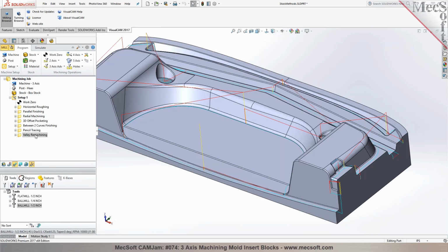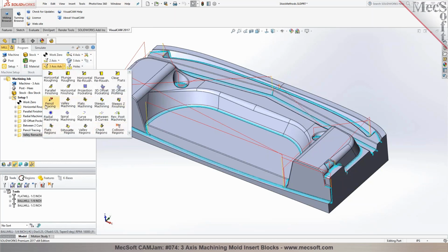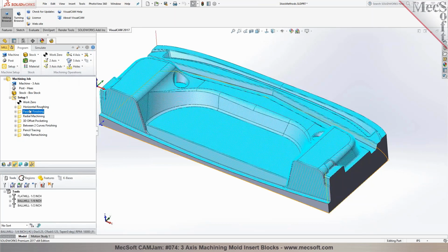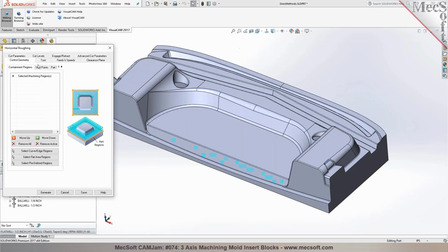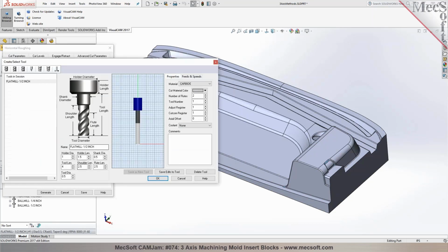There are a lot of different types of methods offered to you in the Pro configuration, where you can choose different methods. You can also do roughing and re-roughing. For example, if you did a roughing operation with a large cutter, I'm going to switch this cutter from a 1/2 inch to, let's say, a 3/4 inch end mill. So I'll add a new tool.